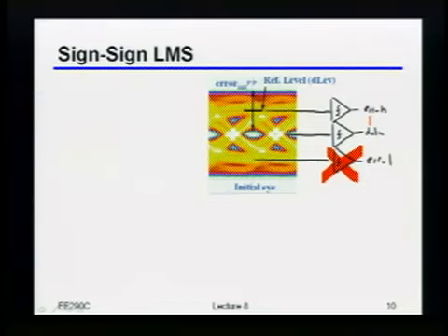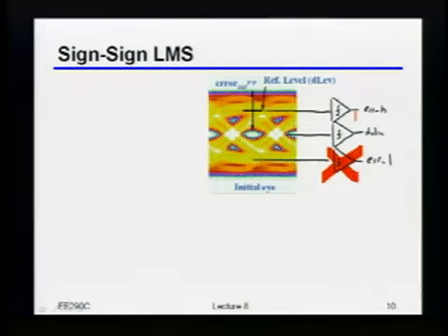Another way of doing it is that you may have way higher resolution in the counters you use to estimate these things than you do in the actual DACs you use to implement them. That's another way of averaging out a whole bunch of these updates before you really make a change at the output. But we'll come back to exactly the issue you're asking about, because it is a very important issue. It's a great question. Other questions on this?